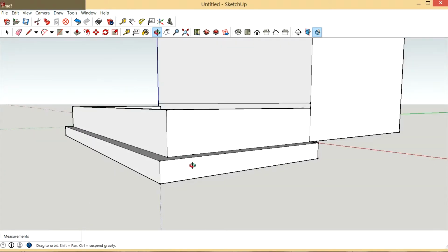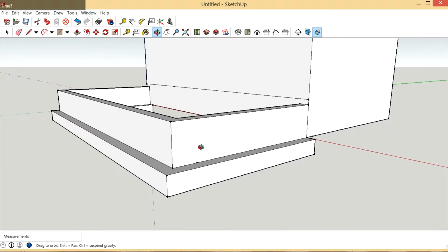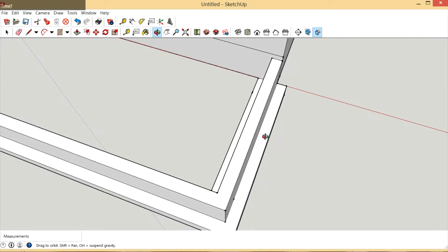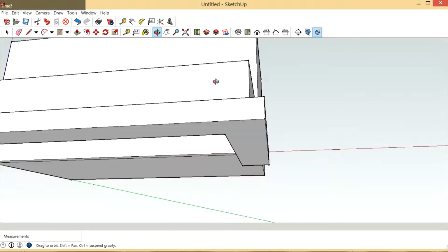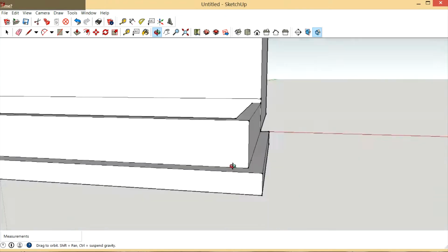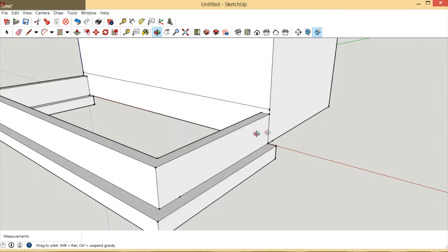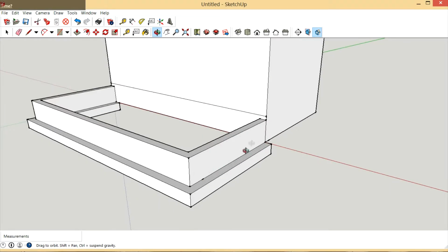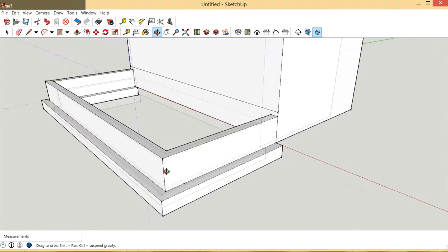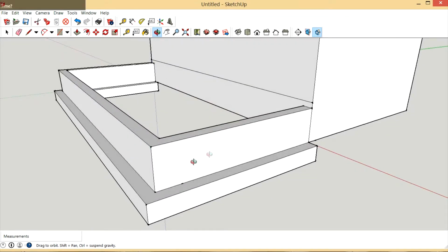So we have this 8-inch concrete block wall that goes around, and we also have our 12-inch thick footing, and it can be 8 inches. I just like them 12 by 24 inches wide under here, and that would have 2 pieces of 3/8, or if you're like me, 1/2-inch rebar running through it all the way around. And then of course this would just be 8-inch concrete block.